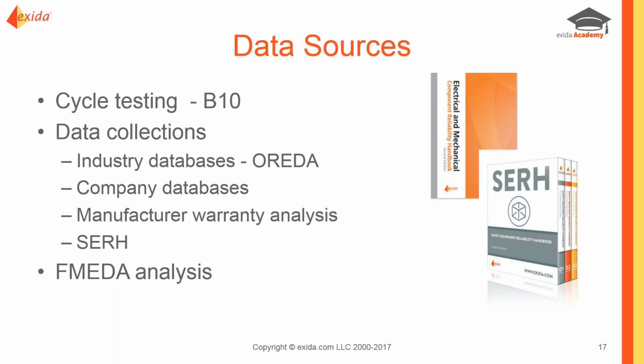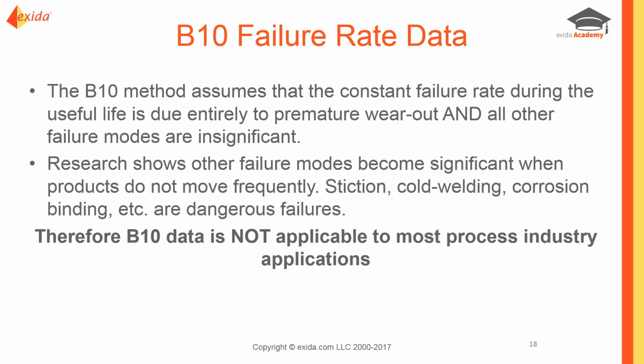If you want to do FMEDA analysis, those are typically done on individual devices, and that activity is actually a predictive failure modeling tool that is calibrated to actual component failure history from databases. So if you don't have any other approach for getting data, an FMEDA is certainly one way to look at specific components. And then, of course, there are a lot of components that are certified for use in SIL environments. So we can look to those certificates, but how do we know that the certificates meet all the criteria? We'll talk about that in a minute.